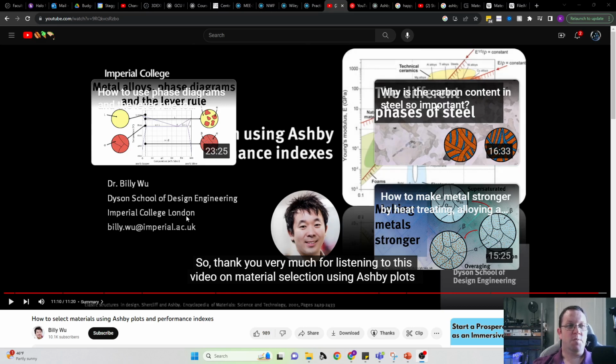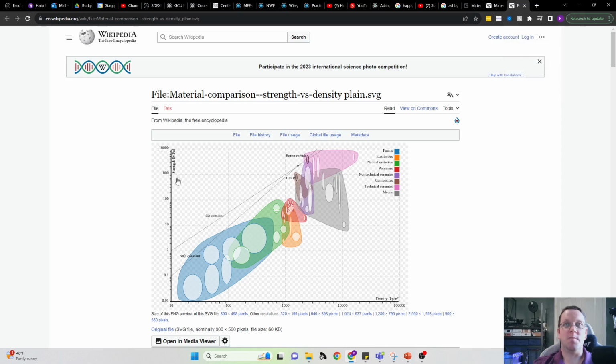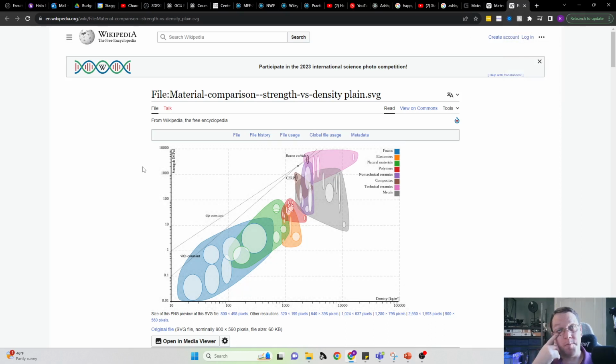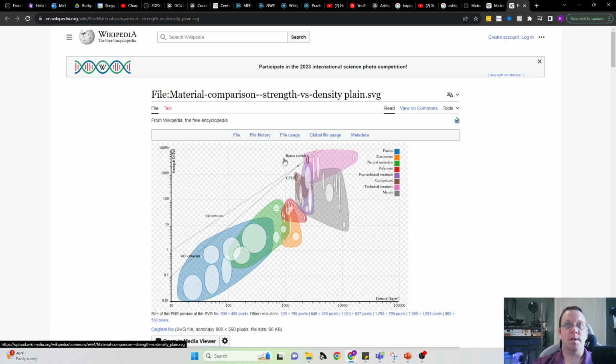So this essentially brings us back to the concept of why everybody ends up effectively making everything out of steel or aluminum. So that's not always the right answer, but when it comes to manufacturability and cost, those are the right answers in a lot of circumstances. So what we want you guys to do is think in terms of, and these are two examples of different types of plots. The square root of sigma divided by density is one kind of line that you can use to decide things.